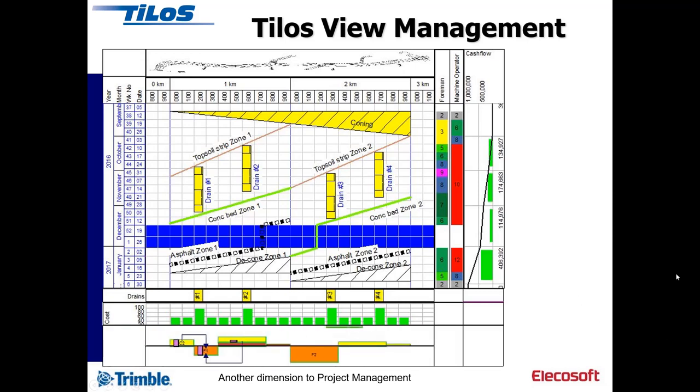And on the distance axis, there's a particular specialism in a diagram called a mass haul, which is where we're going to chop down small hills and fill in small valleys to make a road or a rail bed. And then you can plot how you move soil from one location to another in haulage.